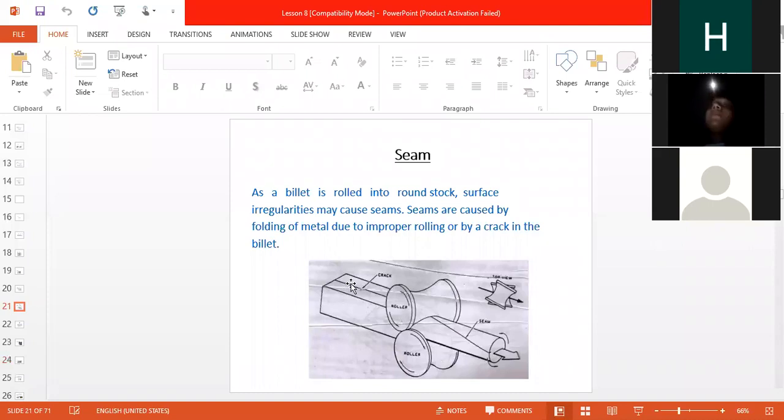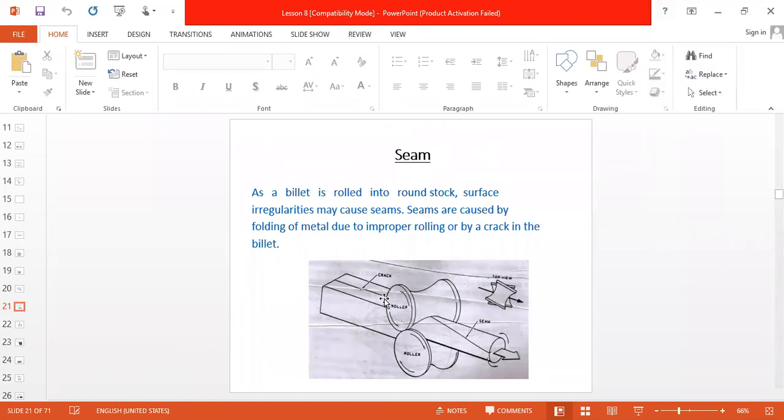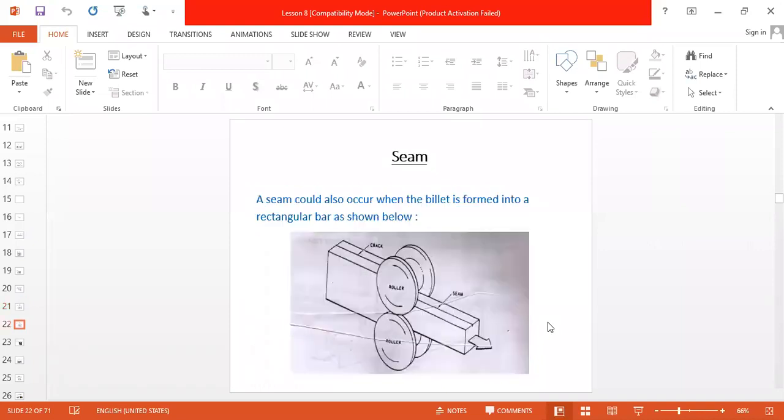Now see here is an open crack on the ingot, and that is not closed in rolling as well. So this defect we can say is a seam, because seam is also a rolling defect. Sometimes what happens, because of roller marks, there is an impression on the job. So that is seam. See, the seam is here.